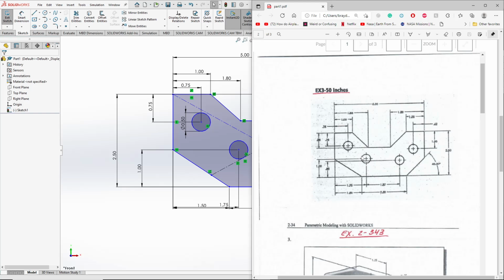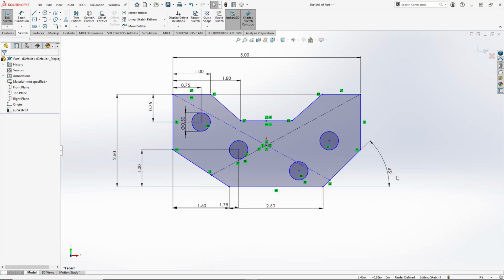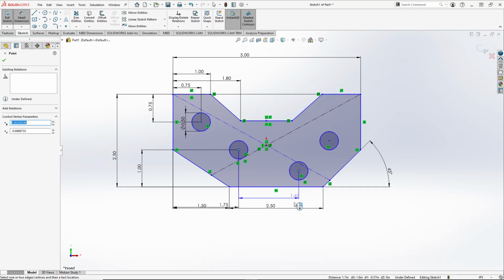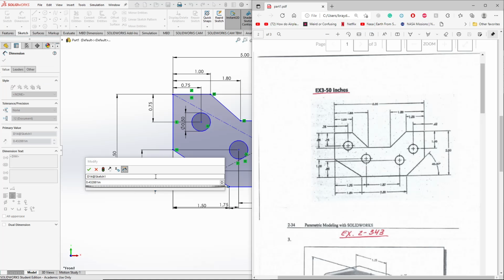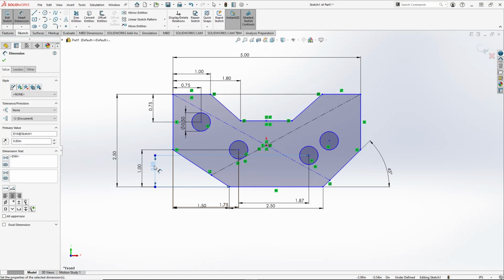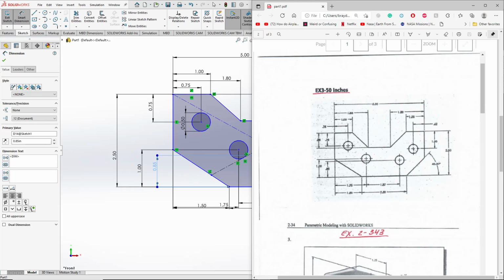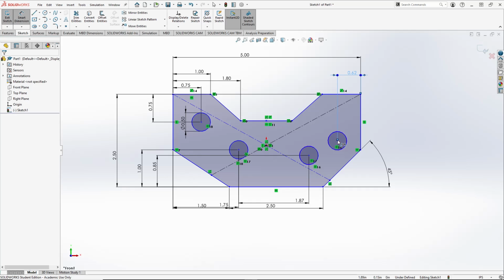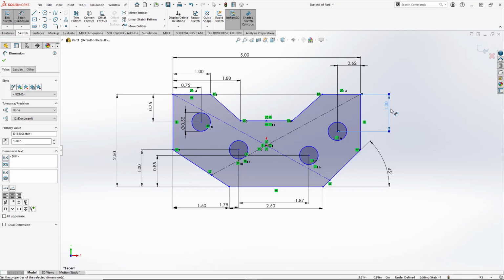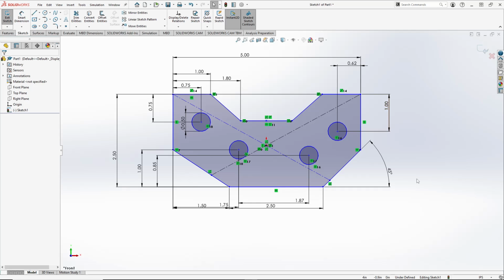Okay, this circle is defined from the center point of the other circle, so 1.87 across, and it is what looks to be 0.85 inches up. Okay. 0.85. Good. And then last one. 1 inch from the vertical and 0.62 from the horizontal. So 0.62, and then 1 from the horizontal. Okay, does it look correct? It does to me.